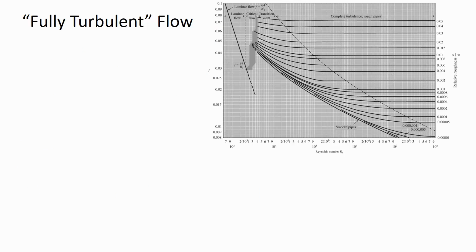Okay, well let's think back to the Moody diagram. There's a section of this Moody diagram where things aren't happening very much, where it gets a little bit boring. Now how could a diagram like this be boring, right? But this flat part's a little bit boring because the F values aren't changing. Look at how level that is. I mean, that's not interesting at all. All you have to do is go with the Reynolds number, find the curve, and then it's straight over. It doesn't really require any judgment whatsoever.